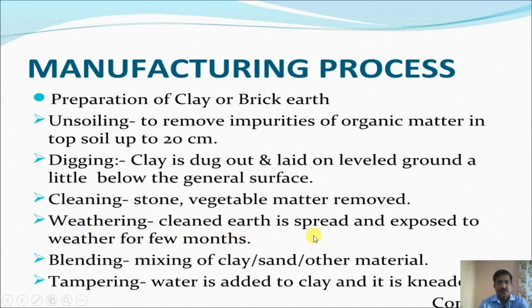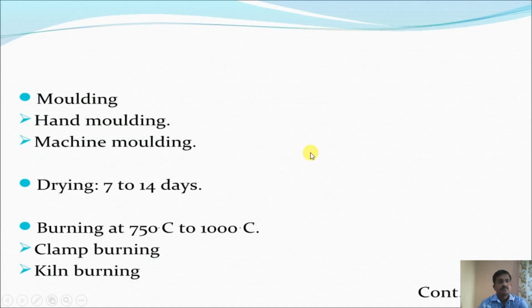Weathering: cleaned earth is spread and exposed to the weather for a few months. Blending: mixing of clay, sand and other material. Tempering: water is added to the clay and it is kneaded. Then the molding process, which may be a hand molding process or a machine molding process.